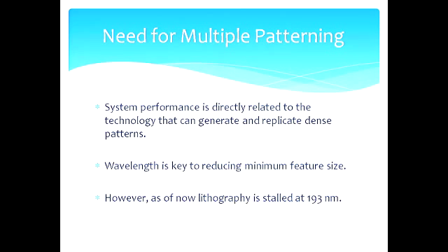So the need for multiple patterning arises because the device sizes are shrinking day by day. The wavelength is not shrinking at the same pace. Reducing the wavelength will reduce the feature size, but as of now, lithography is stalled at 193 nanometers.